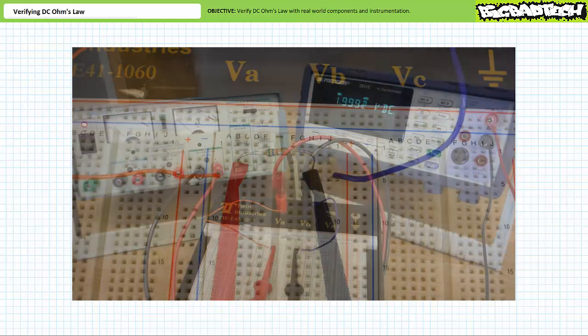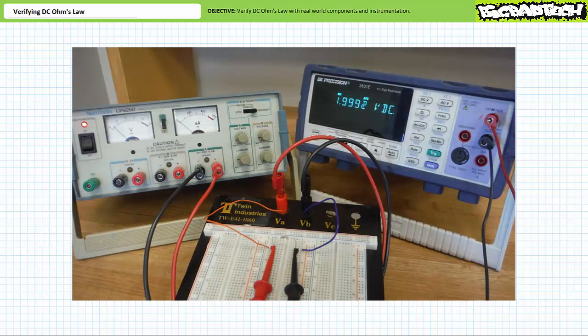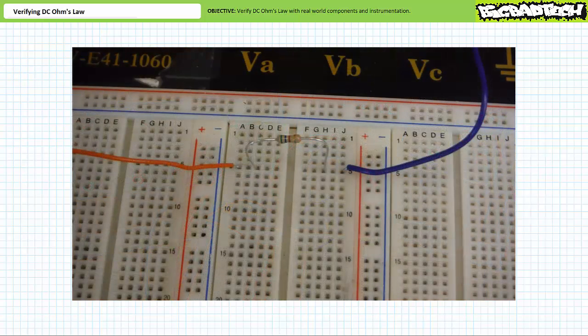Turn on the power supply. The DC voltmeter demonstrates the adjustable source hasn't deviated all that much from the unloaded state when in the loaded condition and actually supplying current to an element. Power off the power supply. Let's now use a DC ammeter to measure current through this system. Consider the original unmodified circuit.